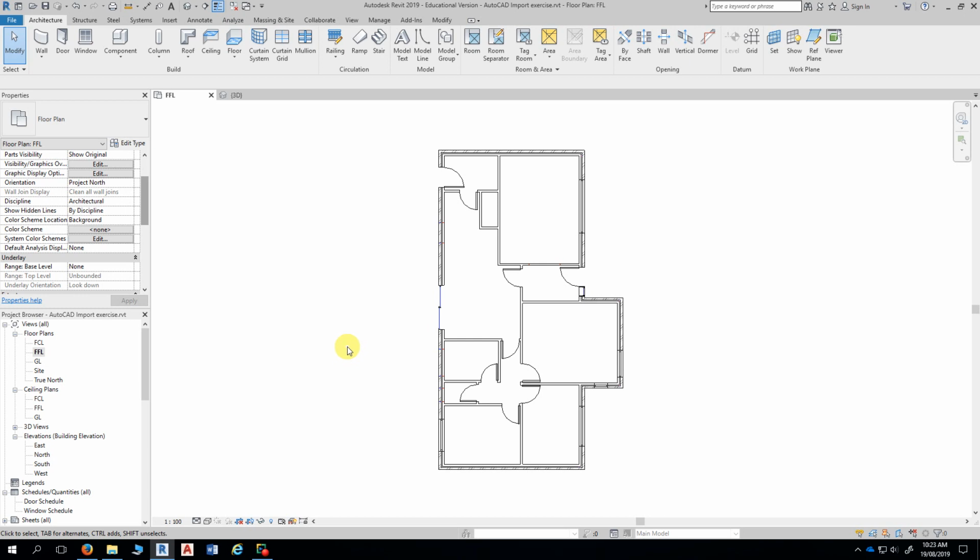So at this stage there's a couple of things that we do. Now, can I ask you to change the visual style of the floor plan to hidden line? Change the visual style of the current view to hidden line. So the question is, what is the current visual style? What are we working in at the moment? What did we change it to in order to actually place the doors and windows? Wireframe. Yeah, wireframe means that everything is completely see-through.